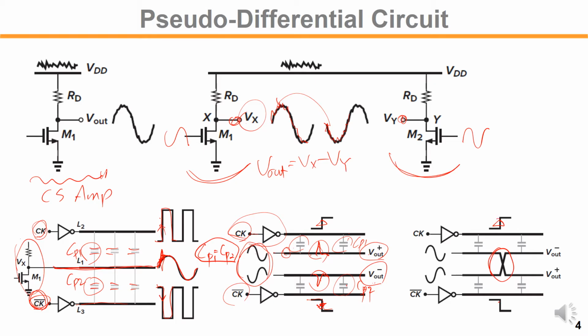For example, if the clock has a rising edge here and a falling edge here on the same line, through this capacitance we have a rising edge coupling, and through this capacitance we have a negative edge coupling. If the rising and negative couplings are happening at the same time, then we can still eliminate those couplings through this cross wire.